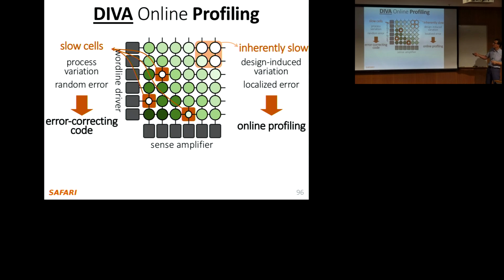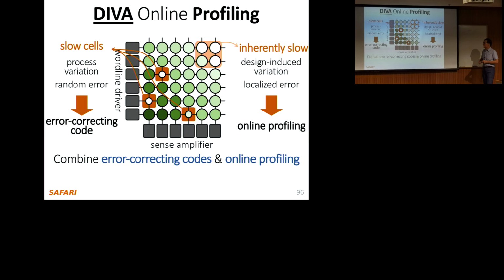The key question is, how do you figure out that region? Well, that's the tough part. You need to reverse engineer your DRAM, or somebody provides that to you. And I believe DRAM manufacturers should be more open to the memory controller. If they are, then memory controllers can figure this out relatively easily. So basically, that's the idea.